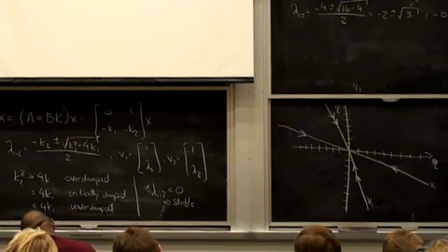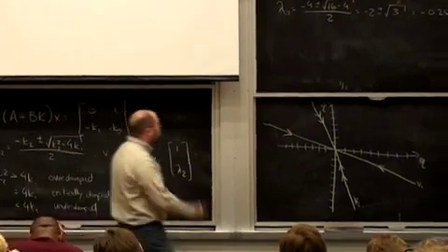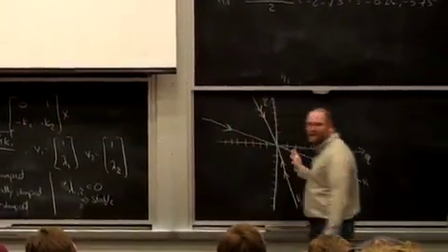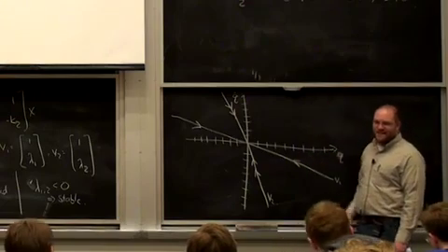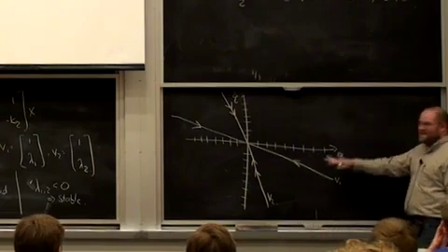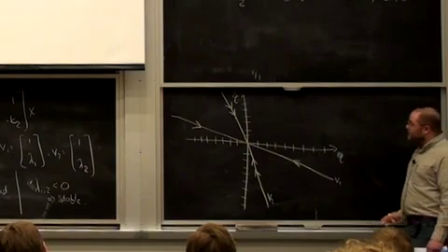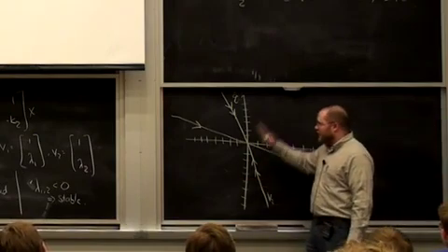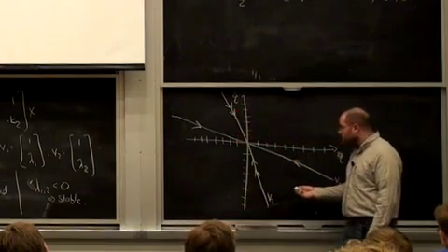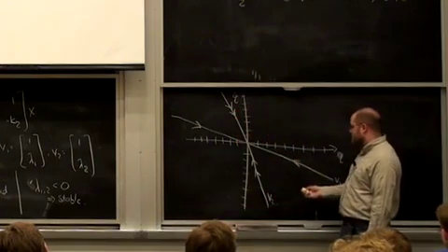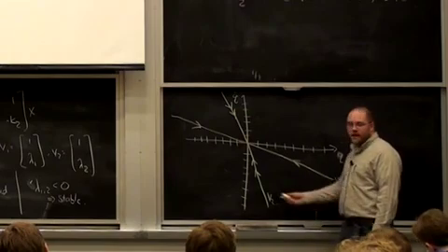Just to say a few of the subtleties, right? So I chose an overdamped system so I don't have repeated eigenvalues, right? I chose an overdamped system so I don't have oscillations because I can't make the same plots. But for the overdamped system, this is a great way to think about things. The reason is that when I don't have repeated eigenvalues, any initial condition of the system can be written as a linear combination.